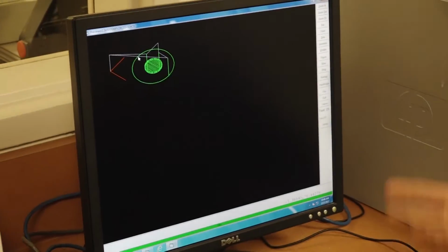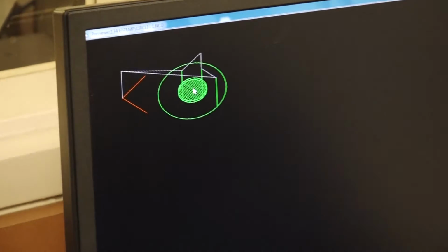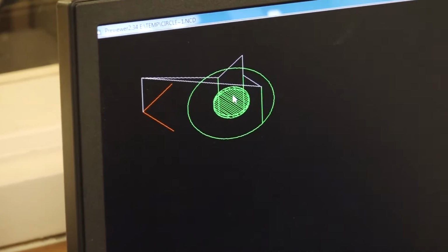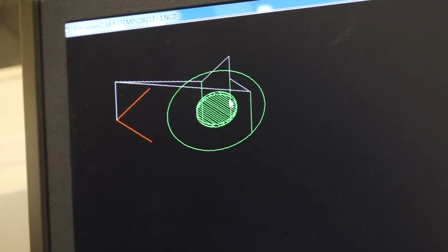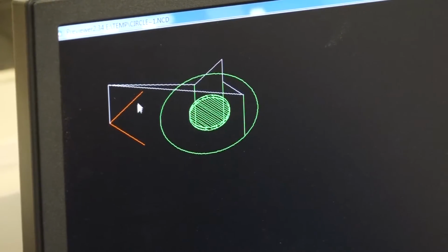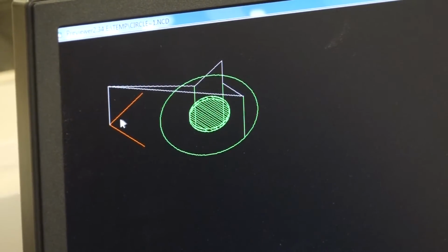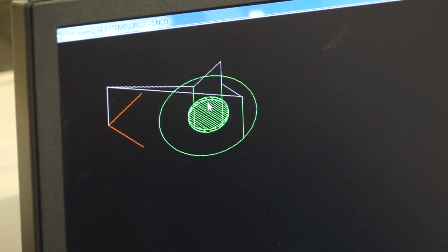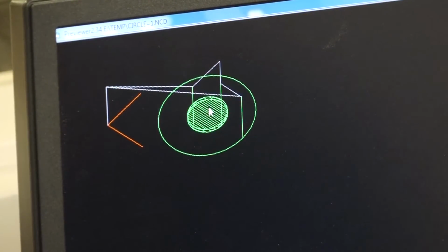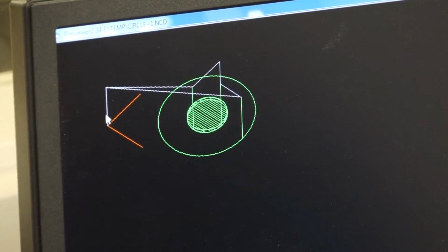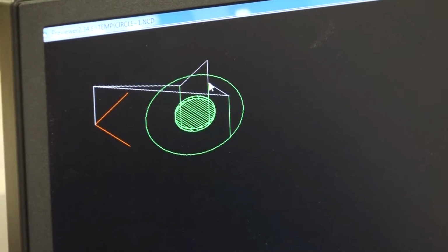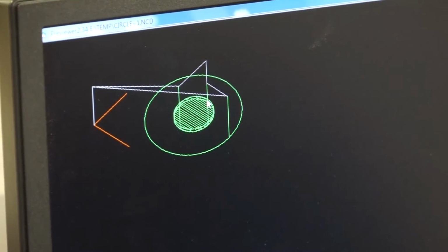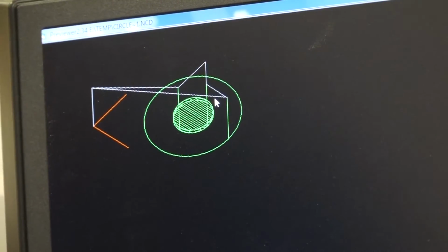Click on it. There's my preview. It's nothing exciting. In this case, I'm going to mill a pocket, a circular pocket, and a circular contour in that little piece of wood that's out there. What it's showing me is that the machine's going to start here relative to where I'm milling, and that's as I've got it set up out there, so that's good. The white means it comes up. All these white lines are where the bit isn't turning. Green means the bit is turning.